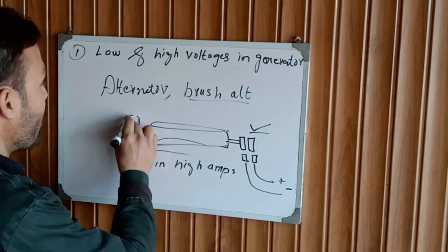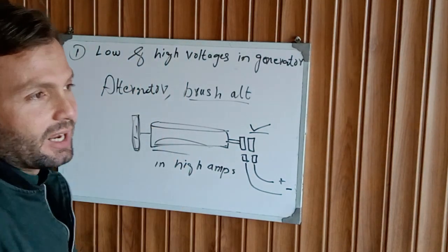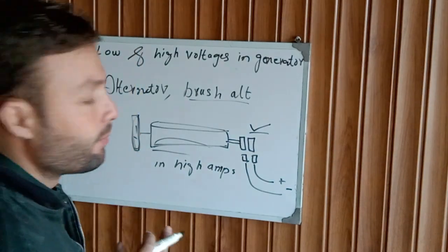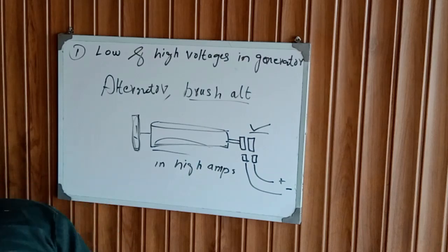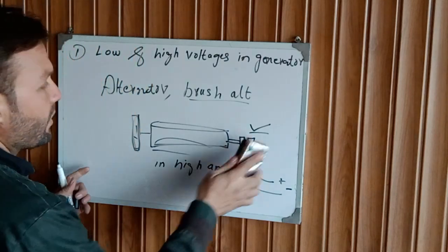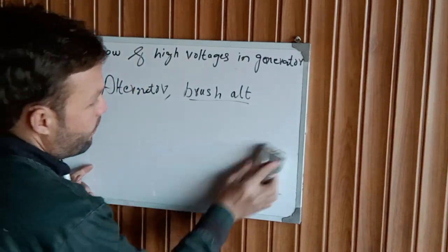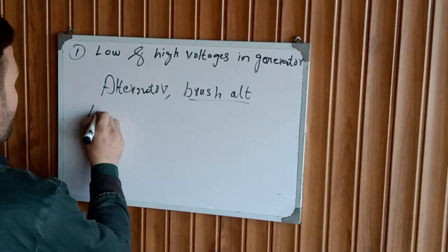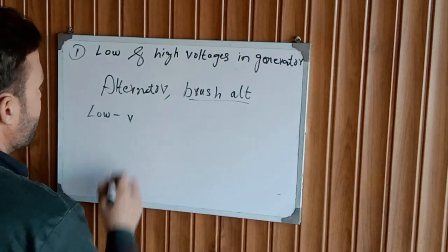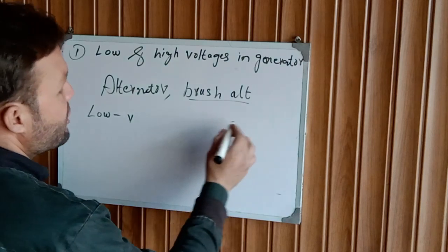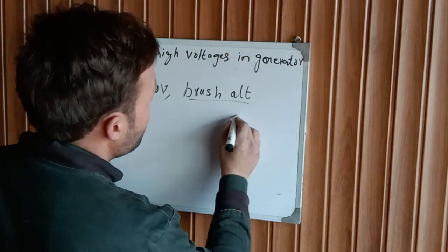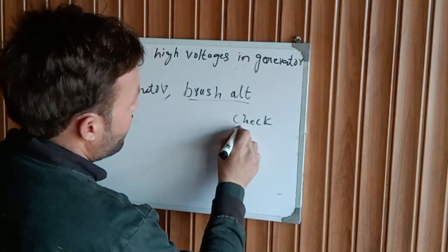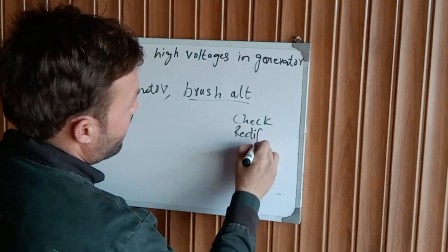If you have a problem in this carbon brush type alternator, here are the problems and solutions. First problem, low voltage: check your rectifier assembly.